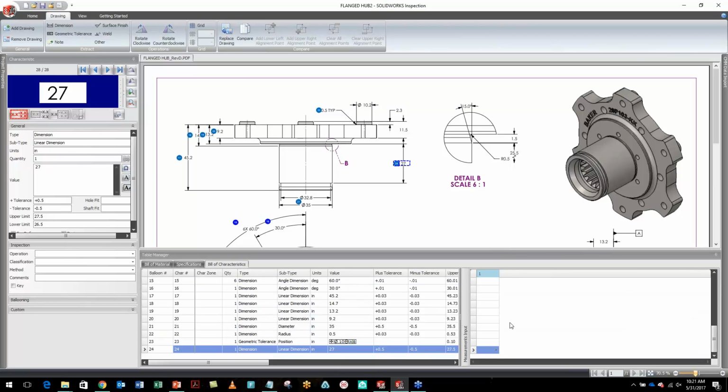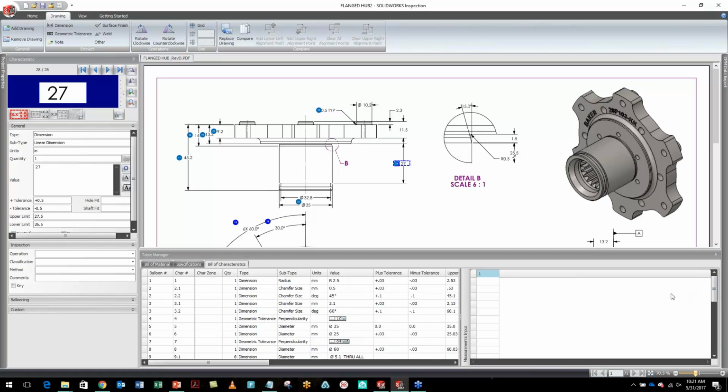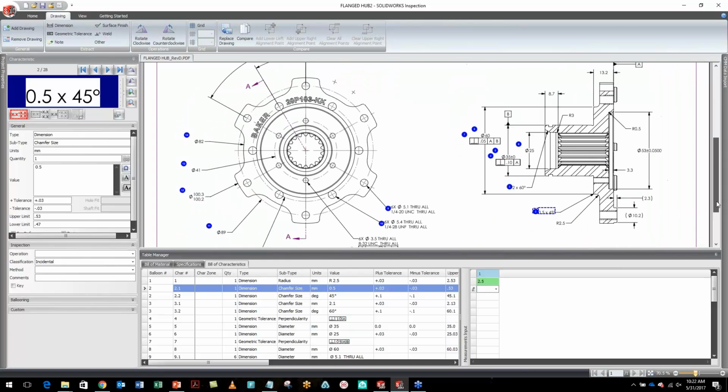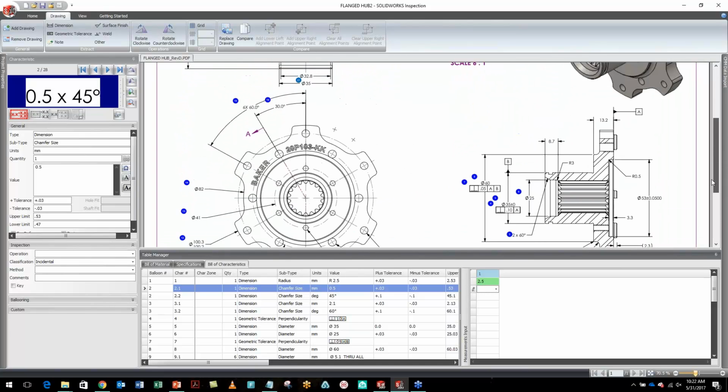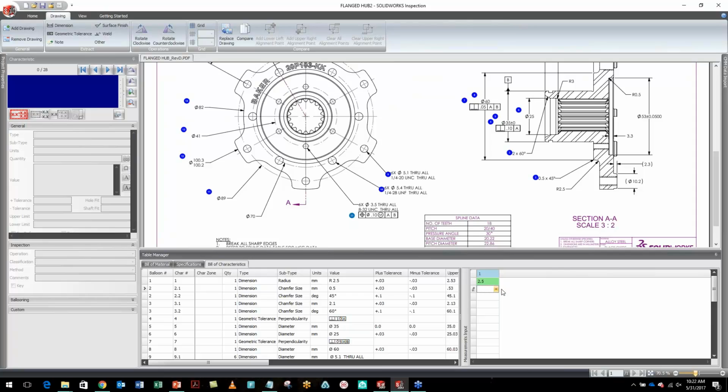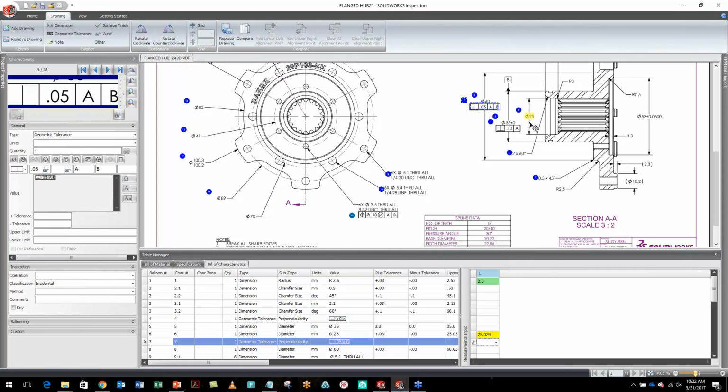So if I wanted to insert any measurement data, there's a couple ways that I can do that. One way is through this measurement input drop box here. If I wanted to, I could simply type in a number. This is going to be color-coded based on pass-fail criteria. And if I go down a little bit further, maybe this 25 down here, I have 25.029. We'll see that that's going to actually show up yellow.